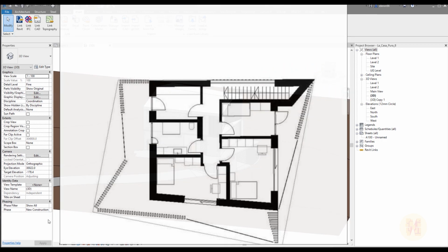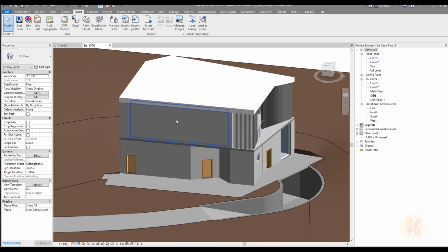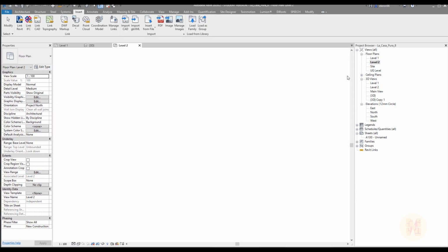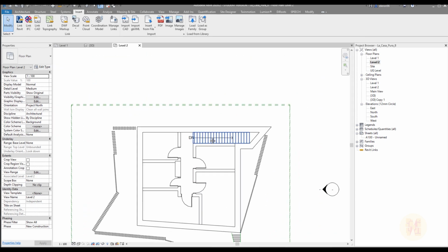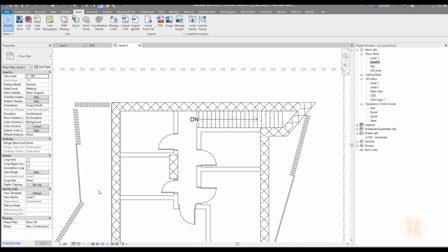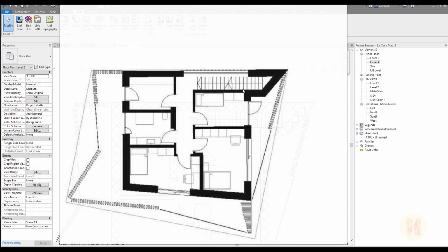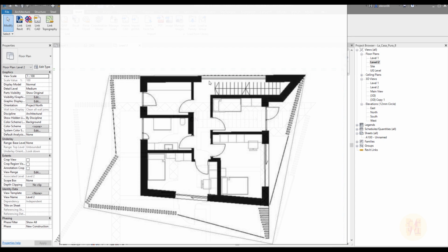The main thing, we should go to level 2 and finish our walls and windows. I will go to level 2 and as you can see I don't have any windows on this level. As you remember, I'm not trying to follow exactly what we have on the drawing, I'm just drawing something like that. All these windows on the second floor are curtain wall.